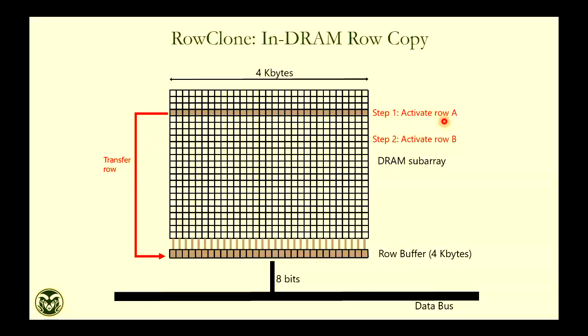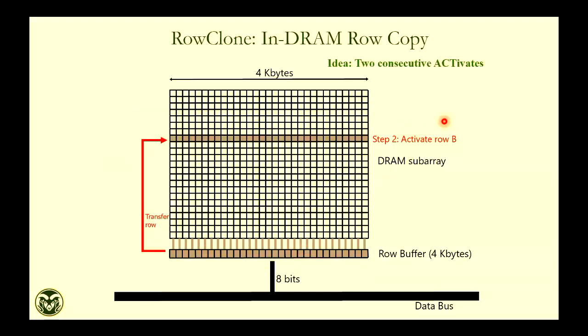You deactivate it. The second step is the write operation, which means you can overwrite. If it is 0, you write 0, no problem. If it is 0 and you have to write 1, then charge will go in, and the sense amplifier will again kick that in. So just look at the write operation of DRAM.